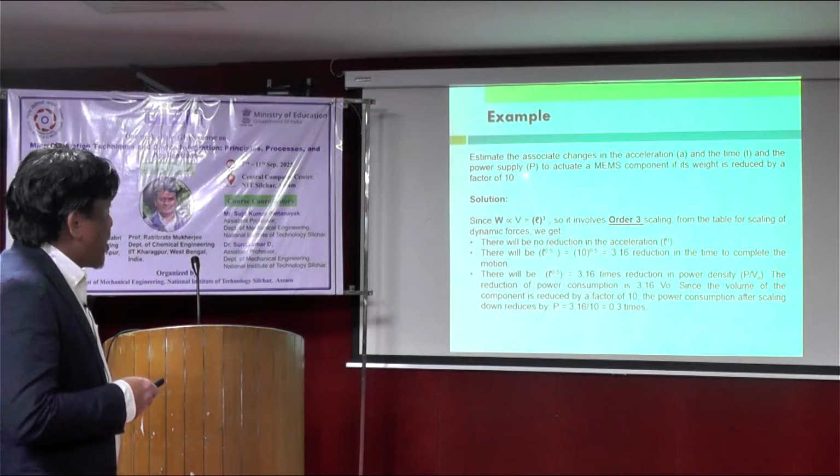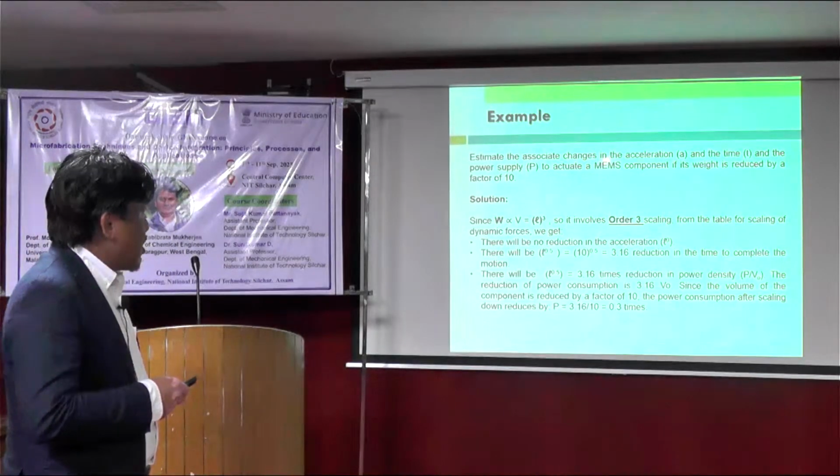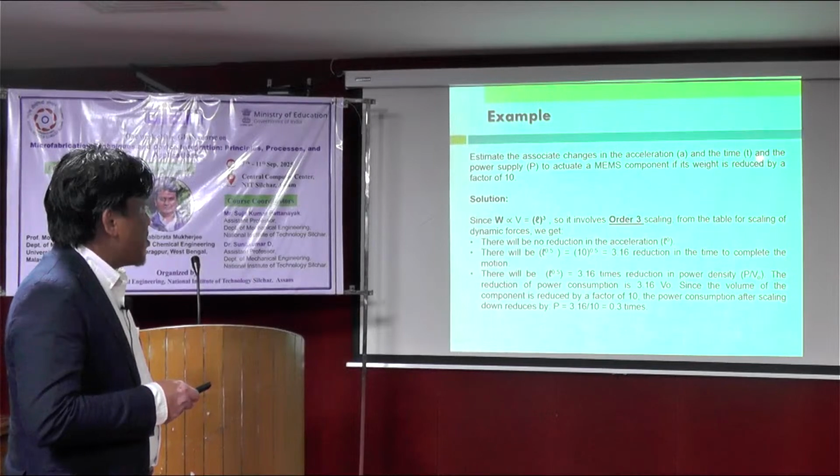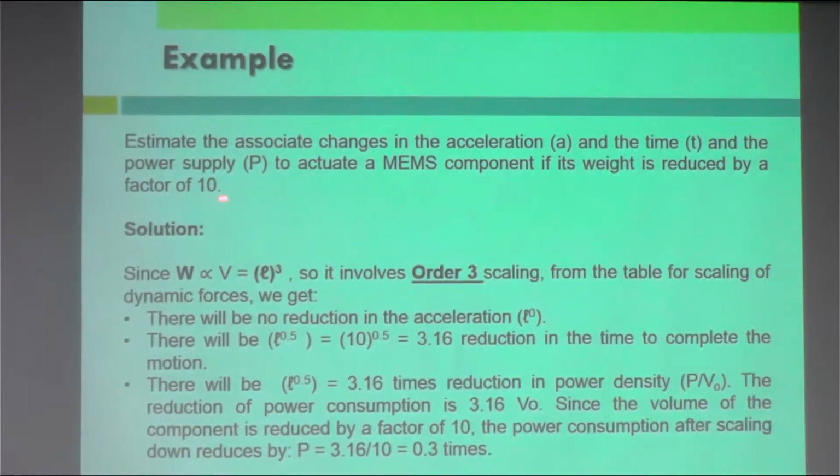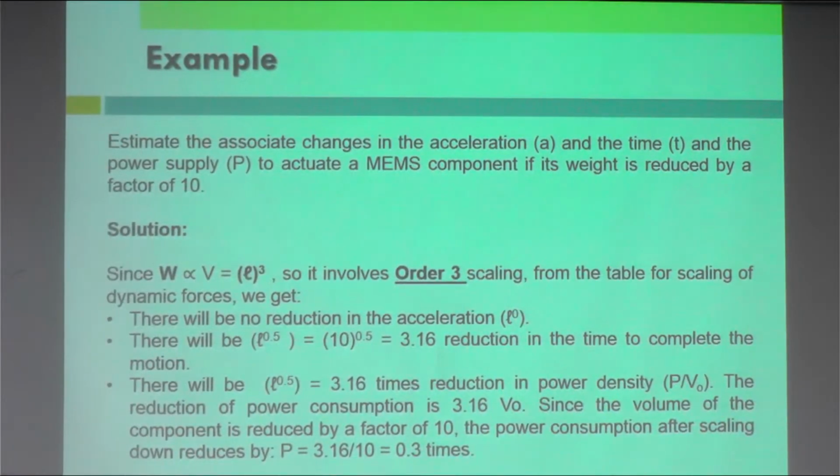And for example, estimate the associated change in the acceleration and the time and the power supply to actuate a MEMS component if its weight is reduced by a factor of 10. So if we reduce the weight by 10 times, not the size, the weight by 10 times, then what will be the acceleration, etc. So you see here, this relationship that we have established before. It involves scaling of 3, the order scaling of 3 from the table.